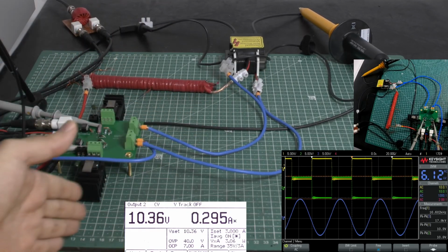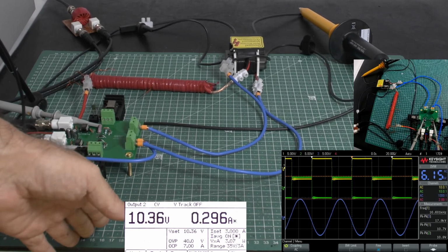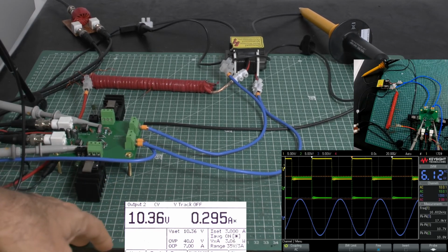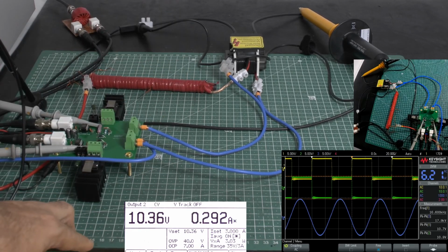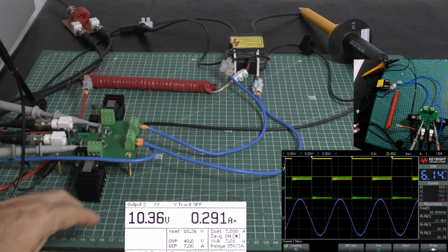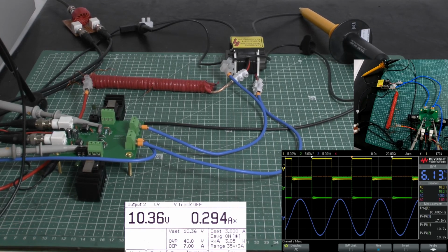However, this wave coming back is a lower energy wave. That means for a Class C amplifier, we always need to put more energy in than we get out. By using two Class C amplifiers working in zero voltage switching mode, as I did here, we can avoid these kinds of losses, and therefore we have a much lower power consumption.